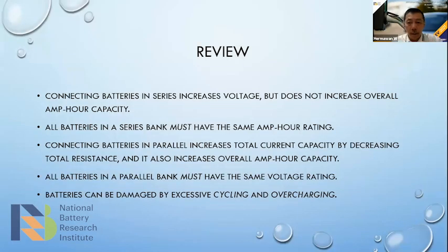This is the final part of the battery pack. It means that connecting the batteries in series increases the voltage. If you want high voltage, you need cells in series, but that does not increase ampere hour. You need parallel connections to increase the ampere hour.